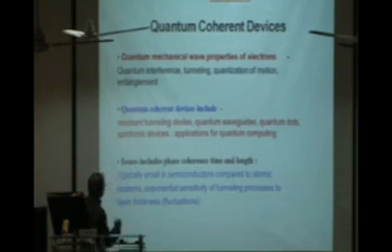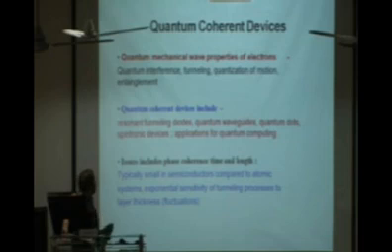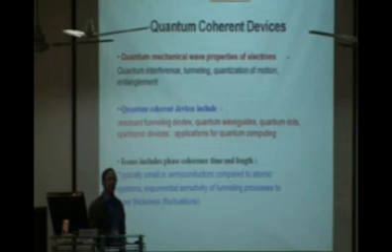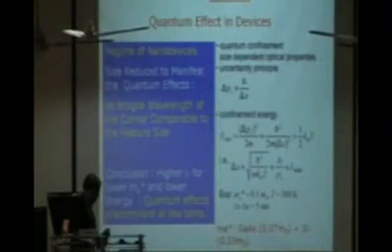Of course, the challenge is that you have to have a very high coherence length or high coherence time. Unfortunately, in most semiconductors this coherence length and time is very, very small. That is a big issue. For tunneling devices, there is a big problem: there is always a fluctuation of the thickness, and the tunneling probability depends exponentially on the tunneling thickness. So it's very difficult to get all quantum dots of the same size or all tunneling barriers of the same width. That creates a lot of problems in making these device structures. Okay, so that is the basic introduction.